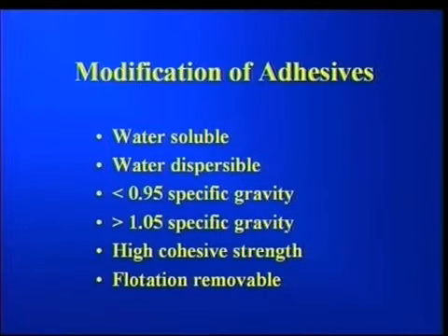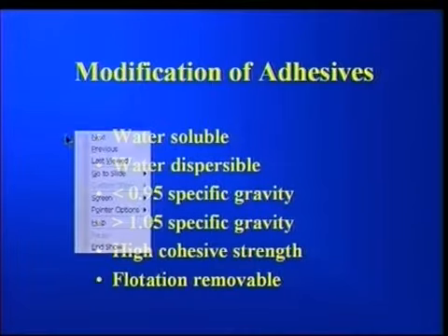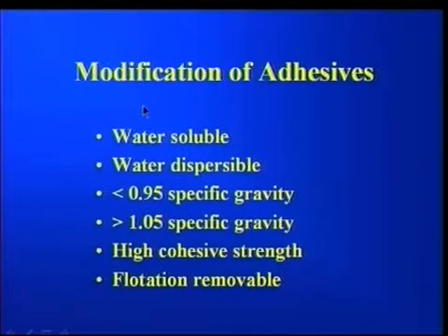And in general, we do not like water soluble adhesives or water dispersible adhesives, but we would prefer the adhesives that could be removed by the use of existing screens and cleaners. And with the help of the United States Postal Service, we have been able to screen various adhesives and come up with a few that could be effectively removed by the use of existing screens and cleaners.